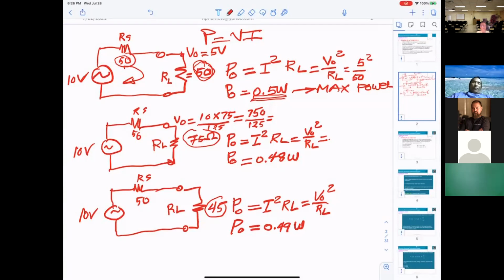If you try to remember, you get CE, CB, CC amplifiers. How come they can get three amplifiers? That's for engineering when they design something. If they want more voltage, more gain, they are supposed to use CE, not CB, not CC.